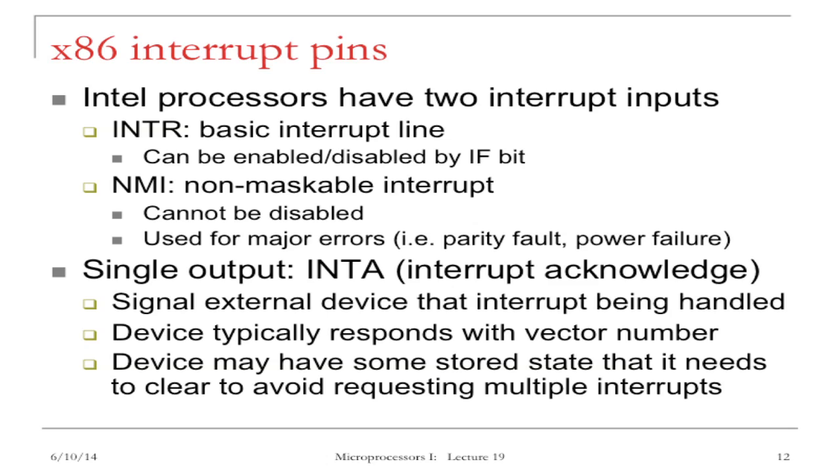The other pin for the interrupt is the NMI, or non-maskable interrupt. This pin cannot be disabled by setting or resetting the IF bit. This pin is used for major errors, for example, parity fault from memory chips or power failure from the power supply.